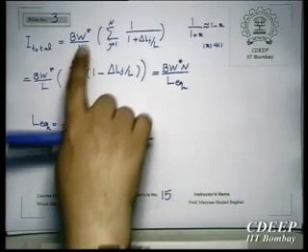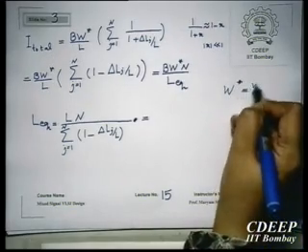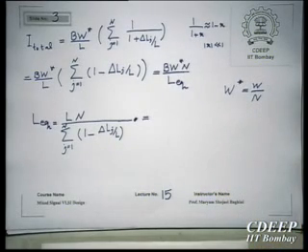These are for the width of W star, but this is for the width of n into W star. W doesn't have any variation. I have divided it into n number of strips and each one of them has the width of W star. W star is W upon n. Now, after all, I have a single transistor with the width of W, which is W star into n, upon L equivalent. The remaining part remains constant. Got it?